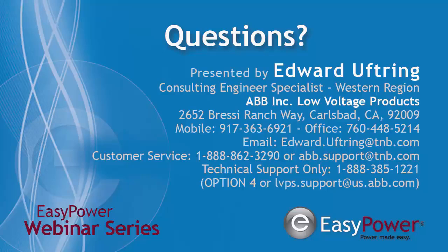So the ground fault protection, basically what we talked about is a short. When you see a phase to neutral or common, or a phase to phase short, is when these voltages come together. Ground fault is when the electronics are actually leaking current to ground, which is a very dangerous situation. We do have a separate curve, and we have separate units that actually do ground fault.